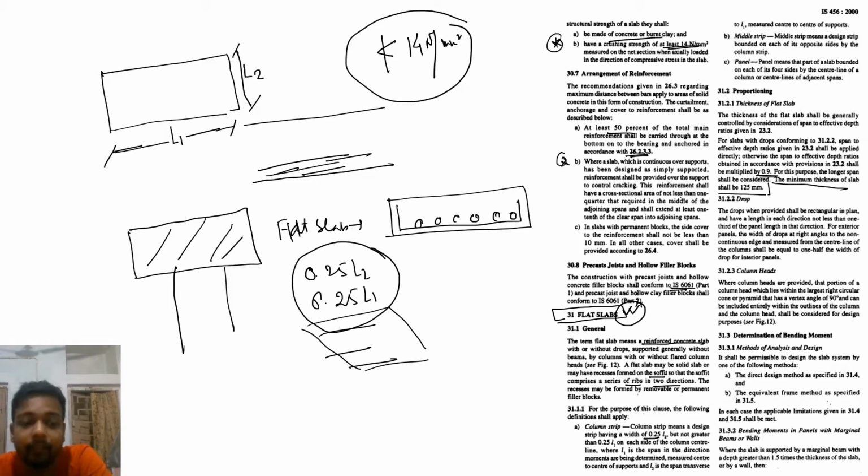So that means flat slab, that means reinforcement. So we normally encounter the flat slab on site because in every slab you find some reinforcement. So minimum thickness of any kind of slab, any kind of flat slab or reinforced slab is 125 mm. That is very much important. Sometimes you find 75 mm thickness. Maybe that is right, but as per IS456 it is completely wrong because IS told us the minimum thickness should be 125 mm.